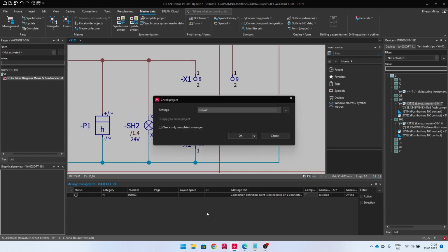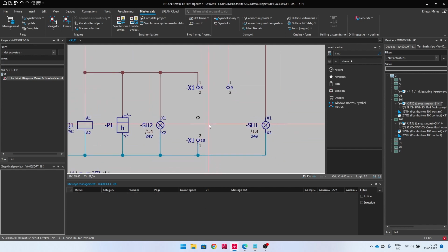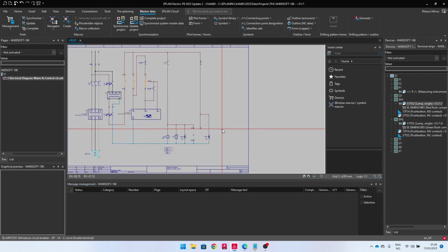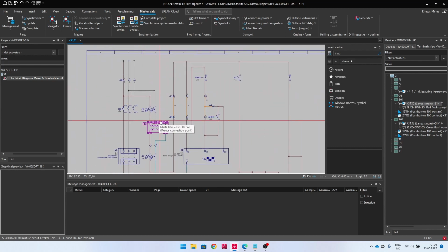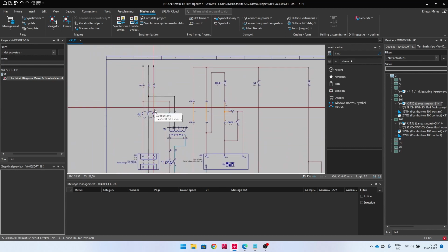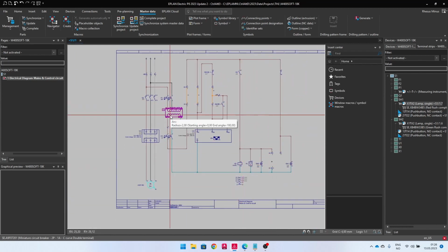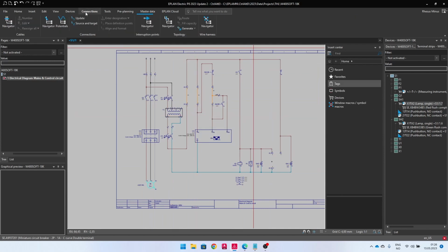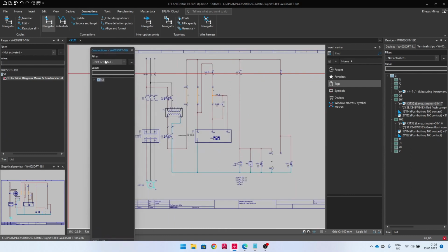So EPLAN told me I have made a mistake. AutoCAD Electrical did not tell me I have made a mistake. So I need to go back and change that in the AutoCAD Electrical stuff as well. But I need to insert some wire thicknesses here, of course. It was like 6 square millimeters up here. And I can do that, of course, using just placing that information. But we're working in a database, so I prefer to do that just in my database directly.